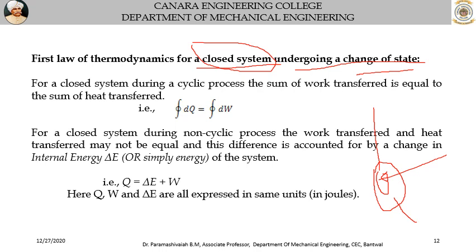Then that energy is transferred to the water and leaves. Energy enters the pump, energy leaves the pump. Water enters the pump, water leaves the pump. If you consider the pump as a system, here both energy and mass transfer take place into and from the system. Such a system in which both energy and mass flow take place is called an open system.